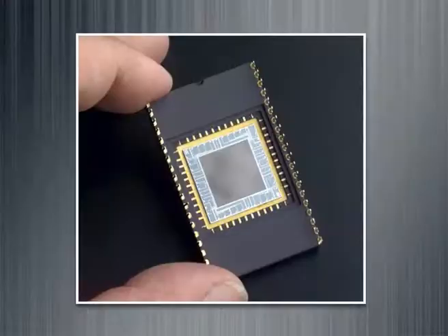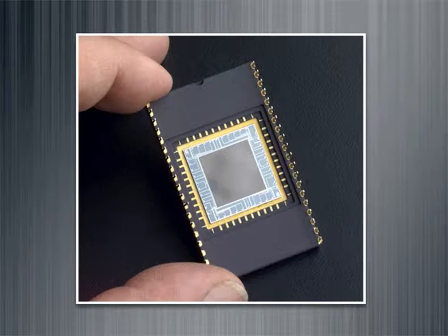This electron packet must then be transferred one pixel at a time through an output node to an image processor, at which point it is converted to voltage. The voltage is then buffered and sent out from the chip as an analog signal. The CCD is small, compact, rugged, and consumes a low amount of power.